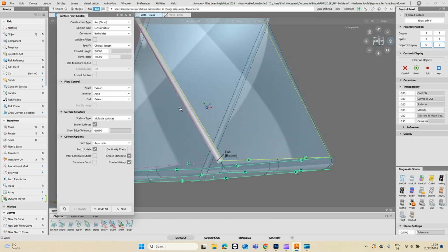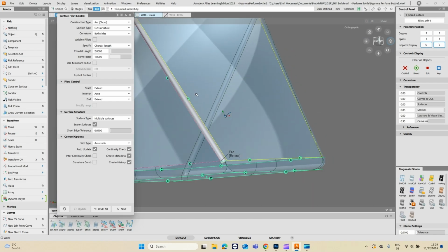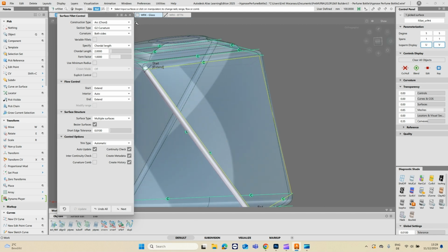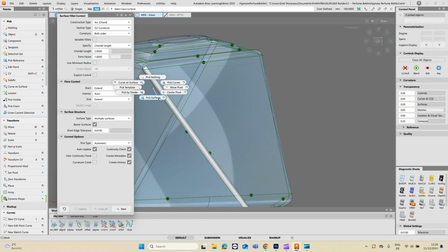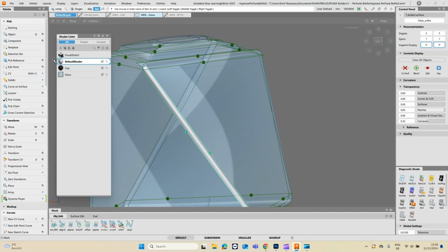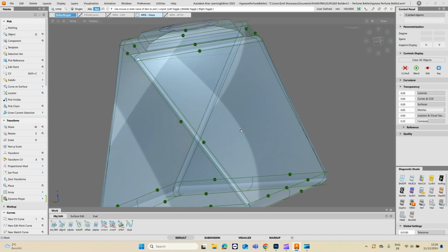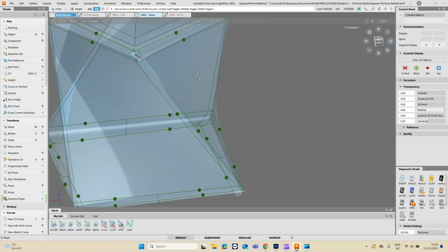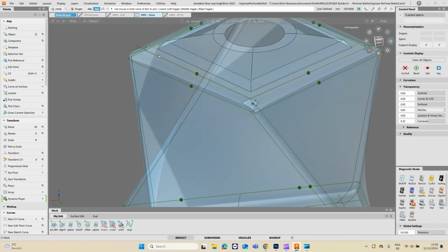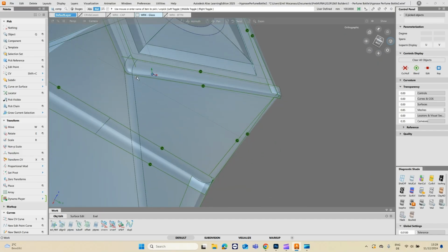This one as well. What I want is a continuity check. So we've got curvature on both sides. Let's take that surface and I'll shade it like that. Because the hardware shader always takes the last shader used for your next generated surface. Because I've just reopened the file, that was the default material, and now if I generate a surface, that's going to be the glass shader.